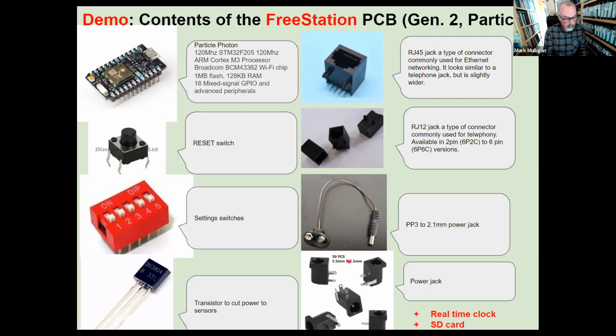But if you're building a weather station that you're going to deploy in the school grounds or anywhere else, it also needs a clock, because if it's not connecting to the internet, it needs to know the time. And it also needs an SD card because it needs to store the data locally and then send it when you reset it. Whereas the classroom demo just connects every minute, as I showed you, and pulls that data over to the internet.